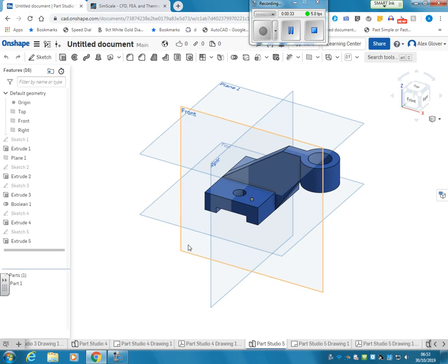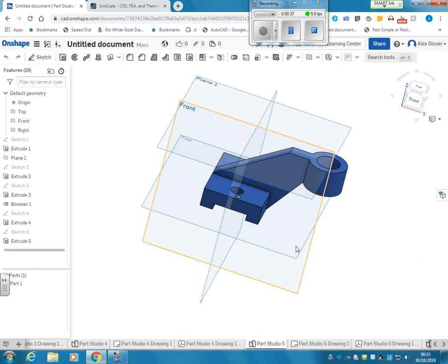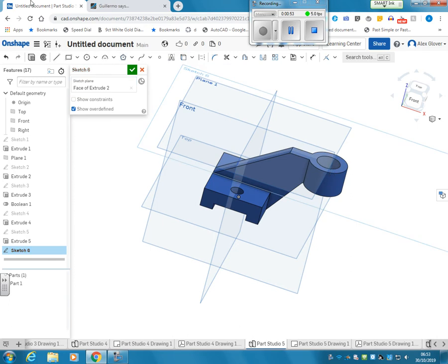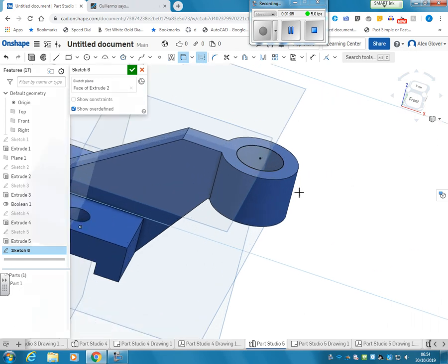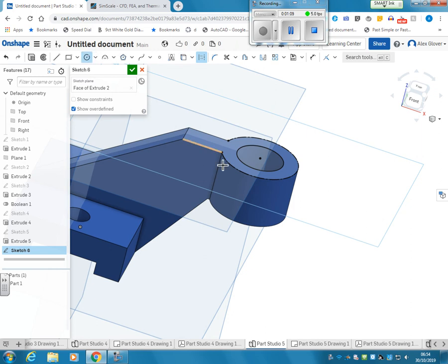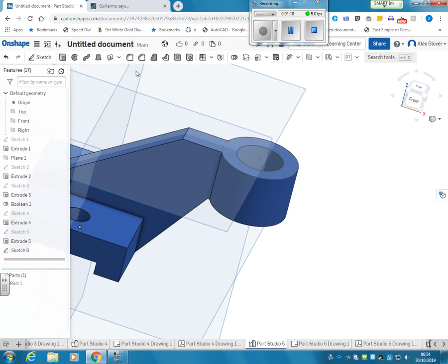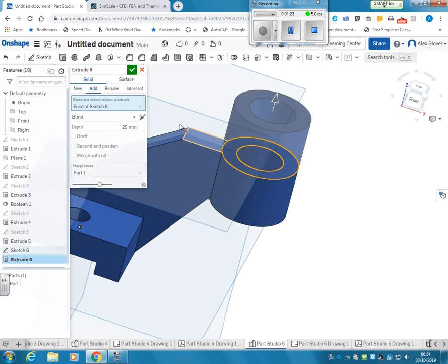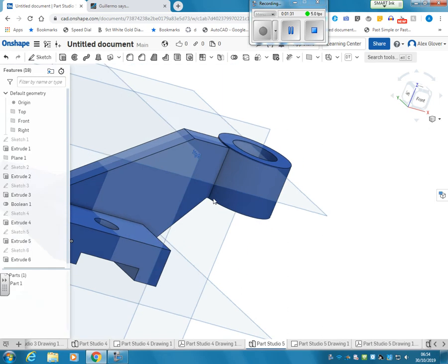It's this drawing. So this part, it was part 5 I believe we did before, and I'm just going to prepare this for the stress analysis just by raising this head up slightly, just to give it an area to load onto. So if I go to sketch here, and then I'm going to pick that, and then construction, the outside, and then choose a circle that goes from the center, get rid of construction, and goes there. And now I'm going to extrude this, not a lot, by about 1/2 mil, so you can barely see it, but it is slightly raised.